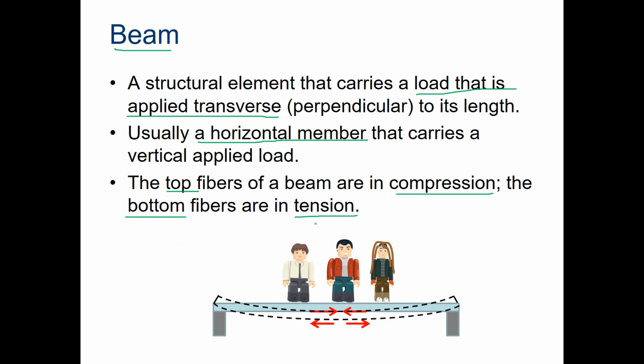And this is actually an important part of a design, this last bullet here, because if you were the structural engineer and you had to figure out where to place the rebar, if this beam is primarily going to be loaded like we're seeing here, then it's important to put the rebar in the lower half, because the rebar is what's going to accommodate for concrete's relatively low failure in tension.